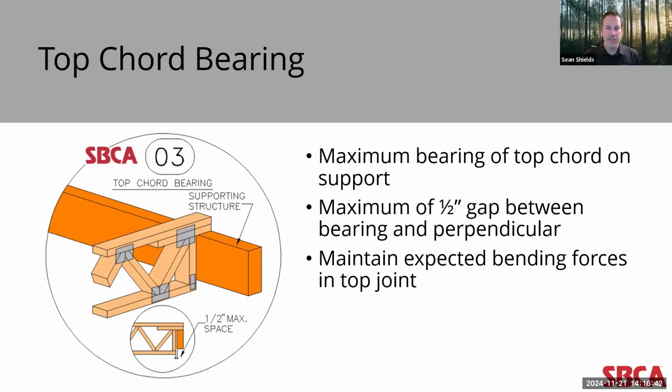Now, this detail calls out a maximum of a 1/2 inch gap between the bearing supporting structure and the first perpendicular web of the truss. This gap is designed as a construction tolerance. It also conveniently allows for the potential application of gypsum for fire protection, fire separation.